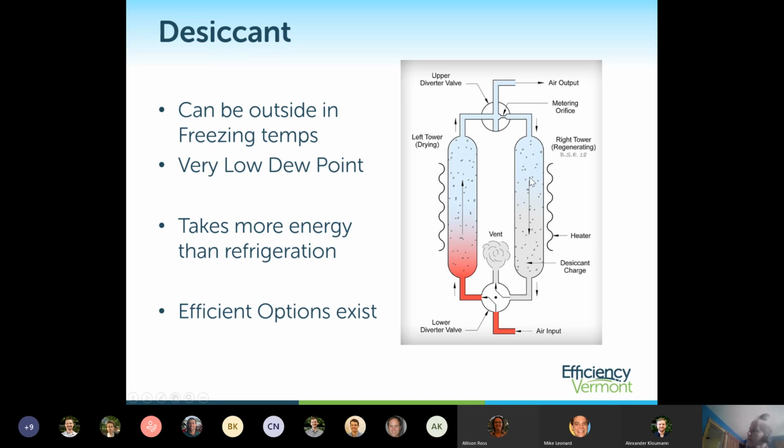While this one is getting moisture off of the compressed air system at the same time. Expelling compressed air is inherently inefficient because you're not doing work with it except for drying the tower.